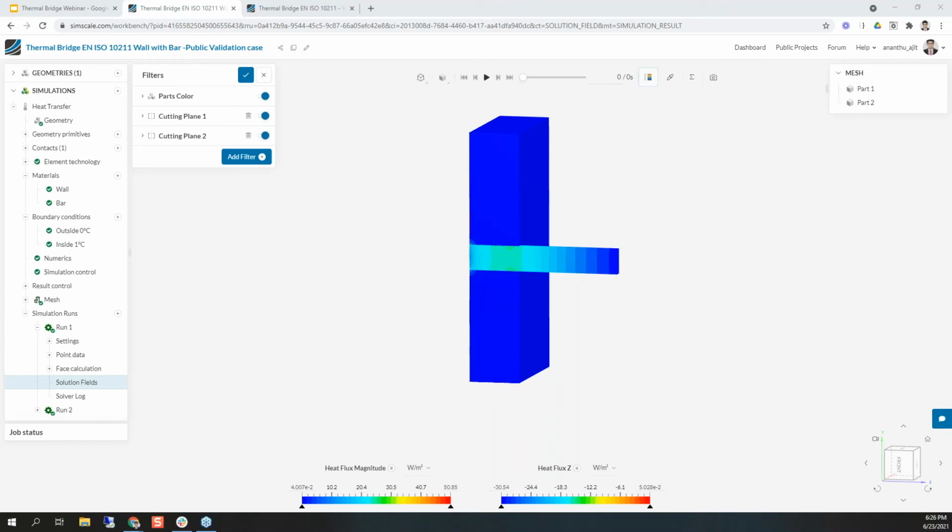So the first question is, can you take into account radiative heat losses from the building facade surface to the outside? Yeah, that's a good question. So right now with the simulation, yes, you can take into consideration the radiative effects. This should be done by using a similar set of boundary conditions that you're going to use. So we can import some sort of formula that mimics the radiation effects, but we don't currently have the explicit feature to set radiation properties on the materials or the surfaces. So this has to be done with a formula-based boundary condition input.